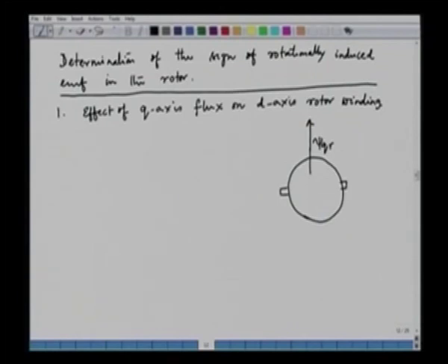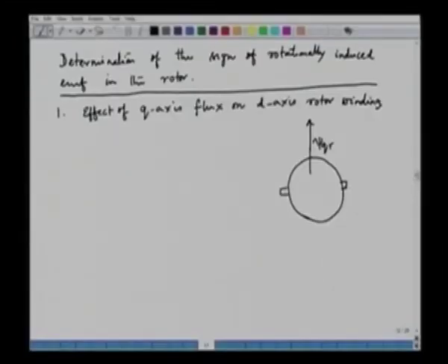Now, as we have already seen, although we have the rotor windings dr and qr, they are called pseudo stationary windings. They are something similar to the windings of a DC machine. So, I can replace the rotor windings by an armature winding having two brushes in the same axis. This is the d axis winding, something like a DC machine winding.